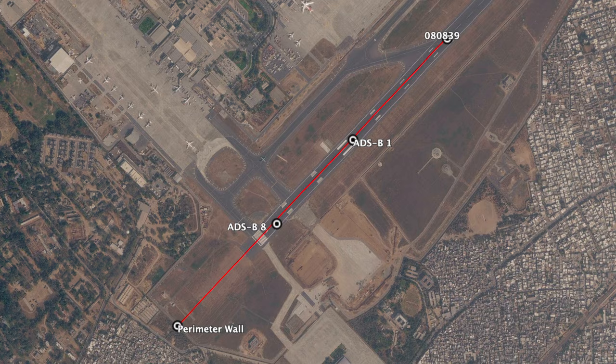As per the EAFR data, both engine N2 values passed below minimum idle speed, and the RAT hydraulic pump began supplying hydraulic power at 08:08:47. Let's start with the takeoff and examine the 17 seconds to the airport perimeter wall.